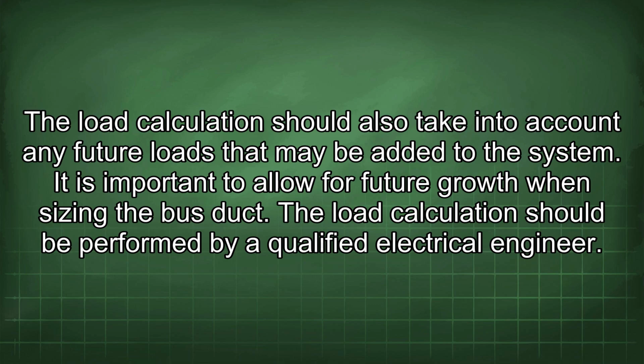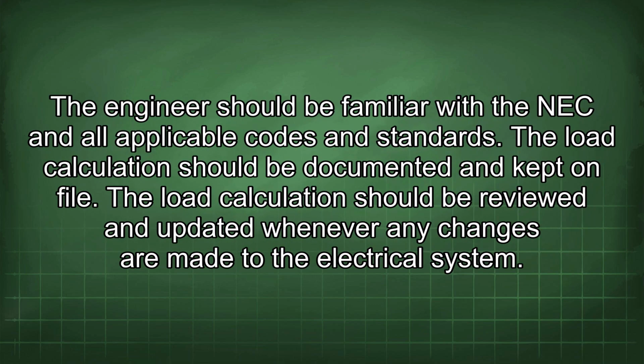The load calculation should also take into account any future loads that may be added to the system. It is important to allow for future growth when sizing the bus duct. The load calculation should be performed by a qualified electrical engineer. The engineer should be familiar with the NEC and all applicable codes and standards. The load calculation should be documented and kept on file. The load calculation should be reviewed and updated whenever any changes are made to the electrical system.